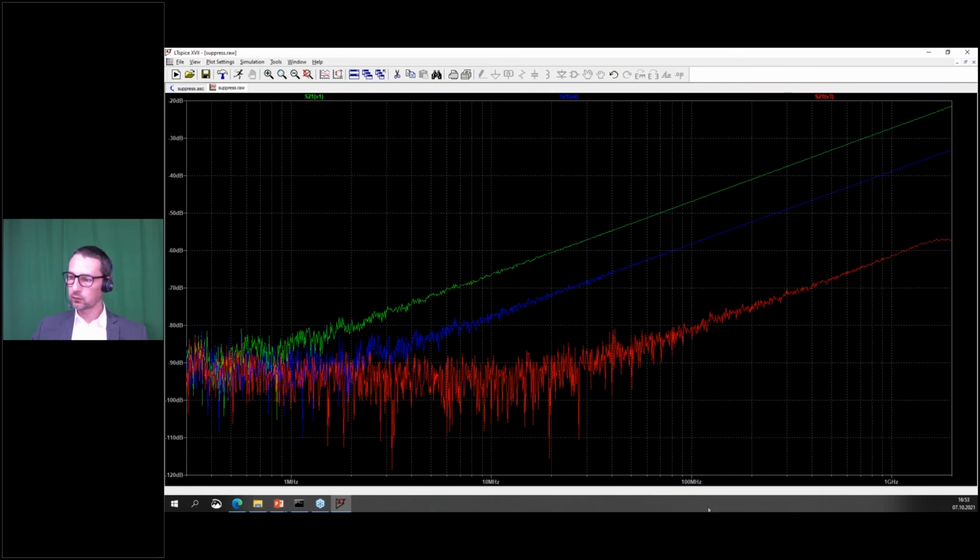And if you want to transfer signal pairs or signals that should not influence each other, this is really helpful and a very well spent space to do something like that. Especially as these kind of connectors are really tiny, so you don't really lose a lot of space if you bring 1 row of pins for grounding into the layout, and it secures you when you want to transfer data on it.